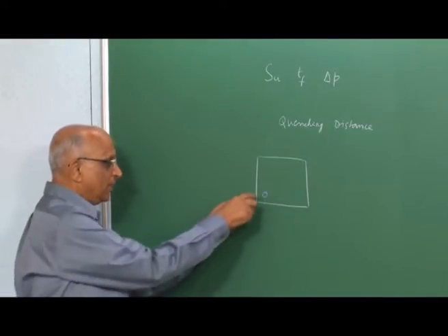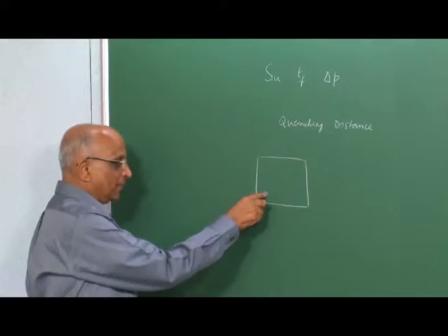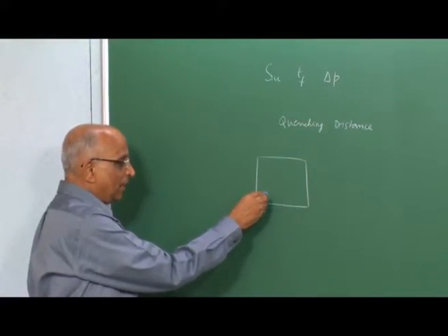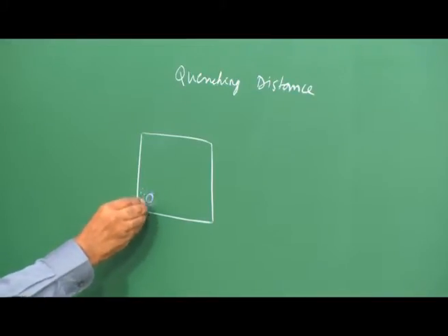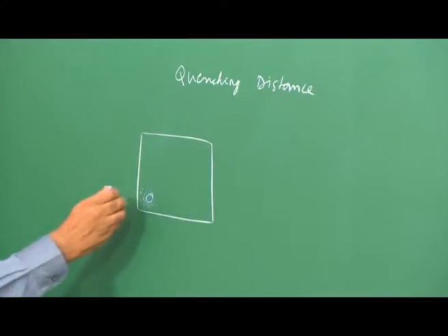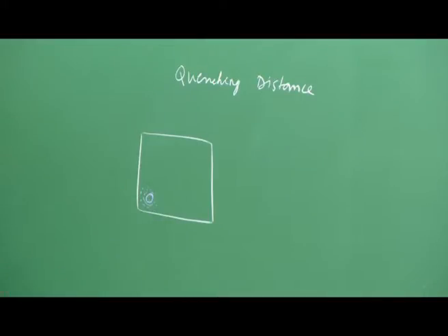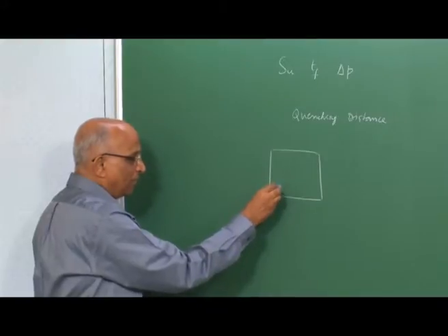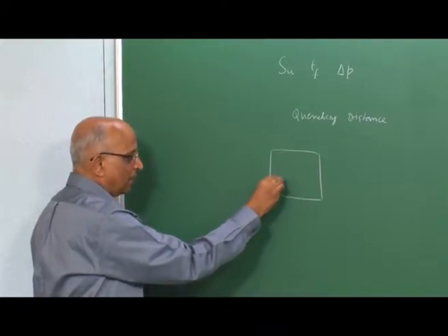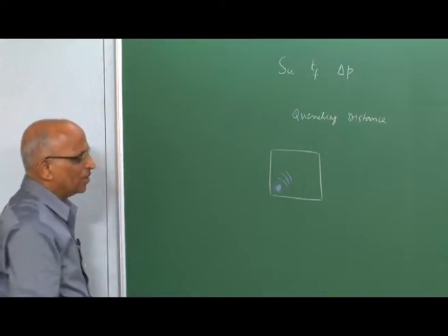We said if this volume or kernel, which we called the ignition kernel, is such that it is not able to propagate the flame, that means heat the adjacent layer and propagate a flame as it were, and it sort of collapses, that means it sort of extinguishes or it quenches, then a flame is not possible. It is essential to have the flame kernel of a minimum size such that it is capable of propagating a flame across. Therefore, we wanted to study this quenching distance.